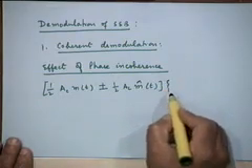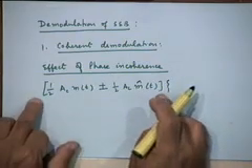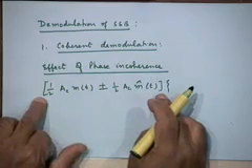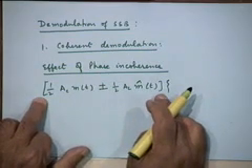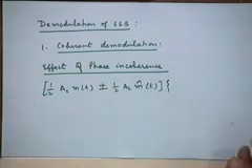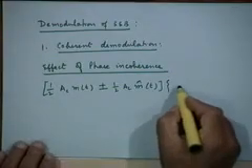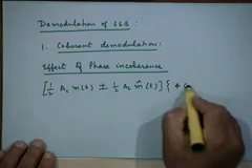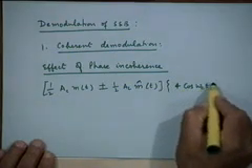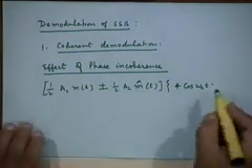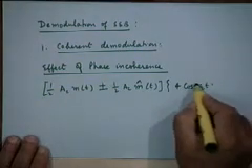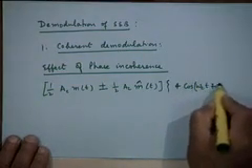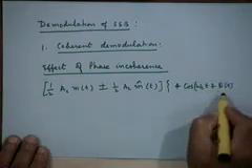In the coherent demodulator you will take this SSB signal and multiply it with cosine omega_c t, and pass it through a low pass filter. For convenience, let us multiply it with 4 cosine omega_c t so that this factor of half and of the trigonometric functions go away. And let us also include a phase offset.